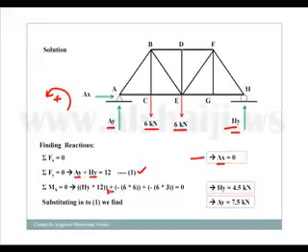Then plus, this plus is just the summation here. Then we have the force 6 multiplied by 3 plus 3, which is 6. This force is going this way, which is negative, because it's opposite to whatever we assumed here. So that's the negative sign right here. The last force, which is 6 kilonewtons, times this distance, which is 3 meters, gives us a negative rotation.